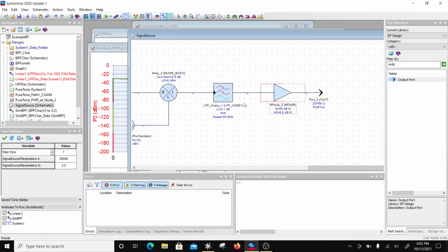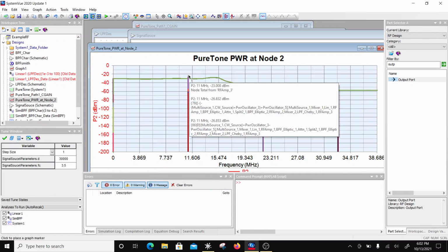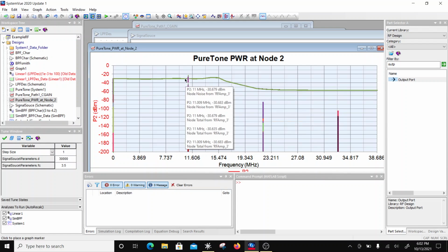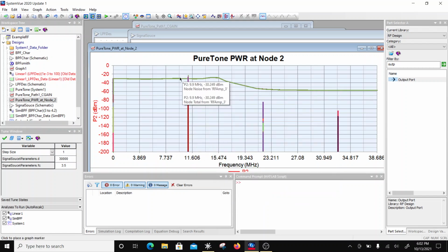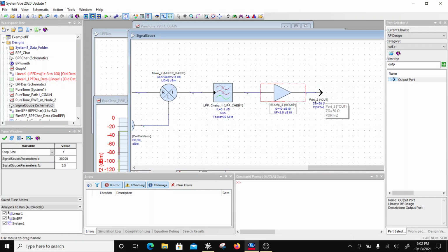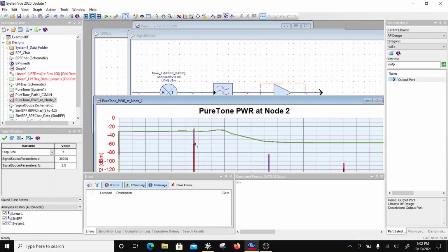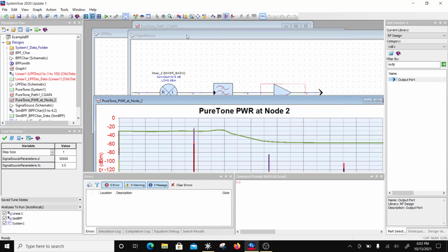Okay, anyways, so here let's look at the signal to noise ratio. The signal is minus 23 and the noise is minus 30.2, so it is around 6.8 dB or something like that. So still at 30 kilometers, if I choose a detector with a signal to noise ratio of 8 dB, worst case, it will still detect a source at 30 kilometers.